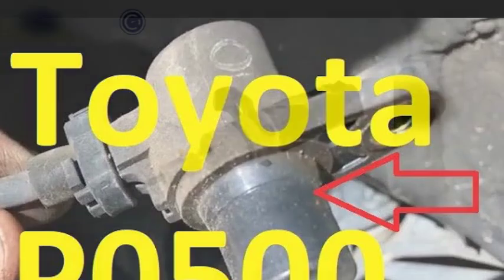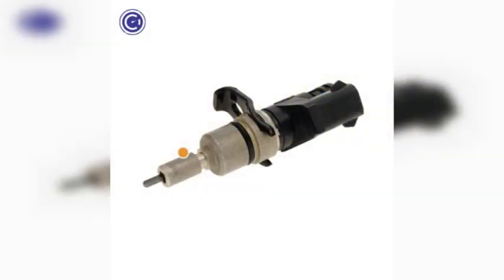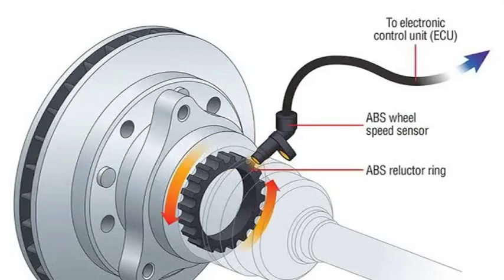The first step is to diagnose the problem. This involves checking the wiring harness for any damage or corrosion, as well as testing the vehicle speed sensor itself. If the sensor is faulty, it will need to be replaced. However, if the wiring is the culprit, you may be able to repair it yourself with some basic tools and knowledge. There are a few different ways to approach this repair, depending on the severity of the damage.